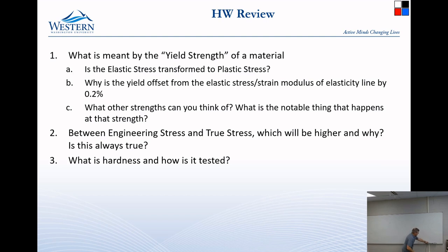So what happens on the graph? If you have your stress-strain graph, it goes up in the elastic region, it starts out in the plastic, and if I let go, it will come back to a zero stress position here. The modulus will stay relatively parallel to the first one.